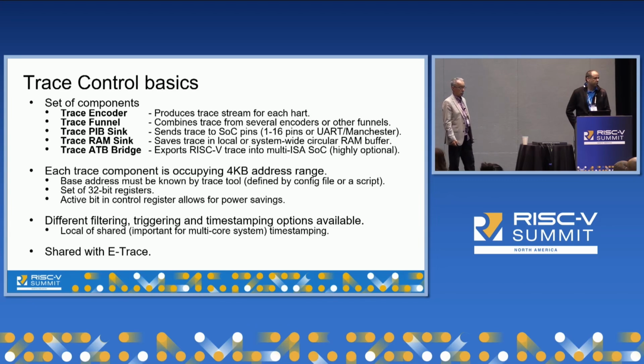This module has multiple different configurations. It can support parallel from 1 to 16 bits of data or even serial transport. And also there is a trace RAM sink, which allows a trace to be saved locally to a small buffer or some type of RAM, or actually to the system-wide RAM buffer.